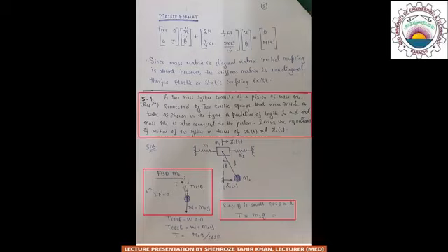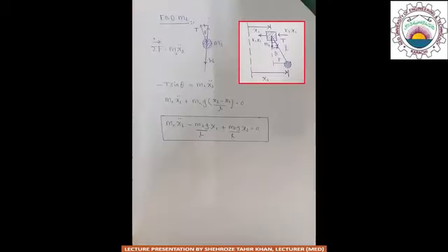For this purpose, the modified free body diagram will be used to study the motion of the pendulum, in which we will also consider the motion of mass m1, which is translating linearly between the stiffness elements k1 and k2. Therefore, we have summation F is equal to m x2 double dot, and here we are taking all the linear forces which are horizontal, and all the forces which are acting from left to right are taken as positive.